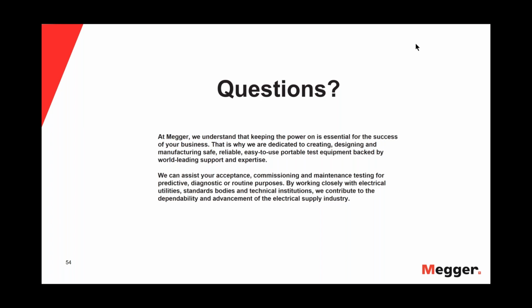However, on ICE, you have the phenomenon of ionization time and these things. So never use the first 1 or 2 cycles for that, okay? Because you will have huge distortions and you might suffer from ionization time. What you also don't want to do is be very far to the right on your screen, which means very long into the oscillation.